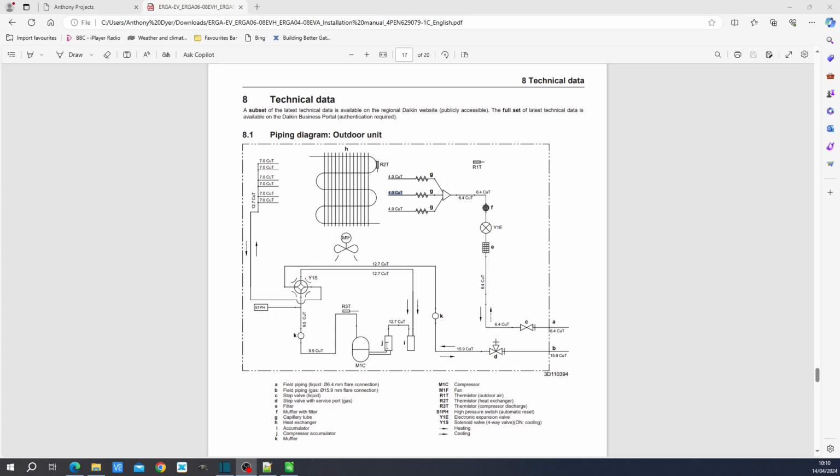So we will take the refrigerant, and we've got lots of refrigerant in these accumulators. We bring it up to a pressure of between 20 and 30 bar, and we drive it through as a high pressure gas and at high temperature through to the hydrobox unit in the house. In the hydrobox unit, we will have a heat exchange, and the high pressure gas releases its latent heat and turns back into a liquid, at which point it returns through this 6.4 millimeter capillary tube on the way back.